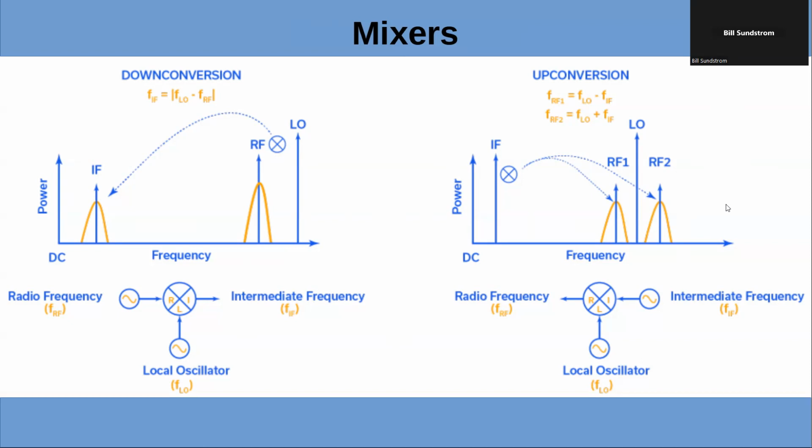If, in this case, why are they showing two? Up conversion. I know, but why? Local oscillator is high frequency, and you're putting in the IF signal. We're feeding the IF and the local oscillator to get these two RFs out, above and on either side, like sidebands.